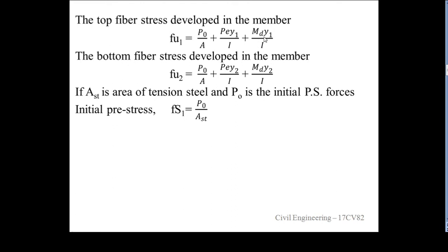This is dead load only. MD is the dead load only. Okay, the bottom fiber stress developed in the member, that is Fu2, is equal to P0 by A plus P0 e Y2 divided by I plus MD Y2 divided by I. Here Y2 represents the distance to the bottom, and Y1 represents the distance to the top.